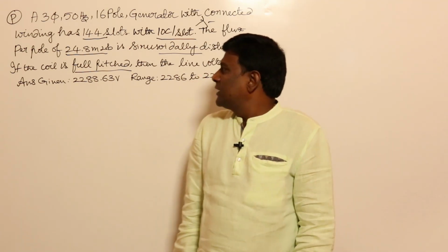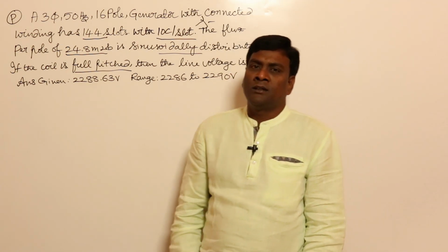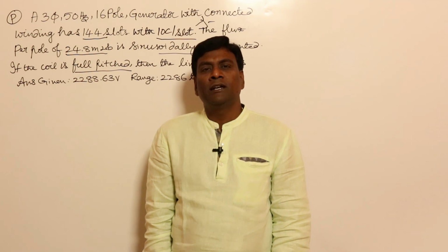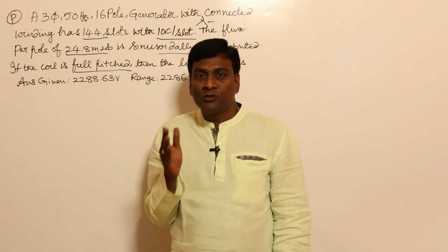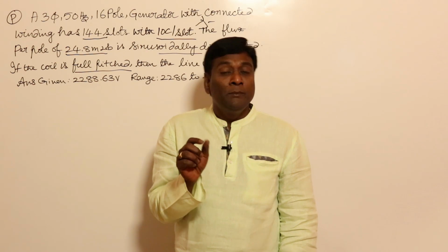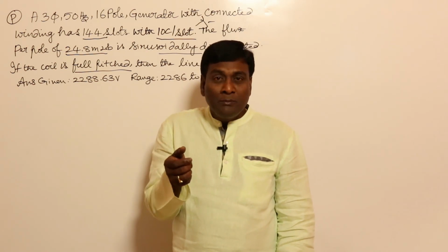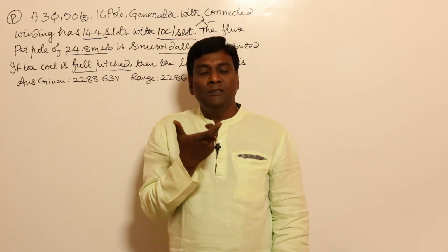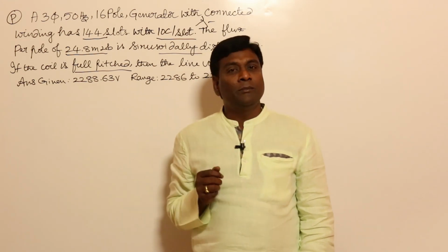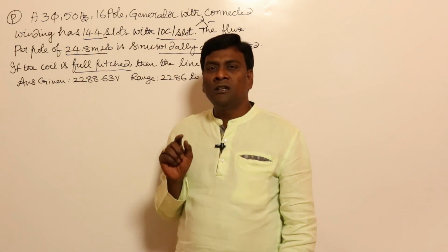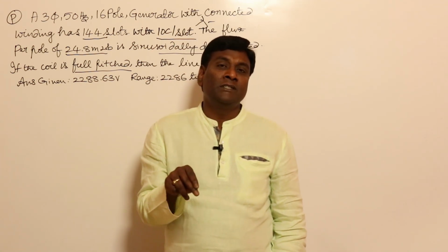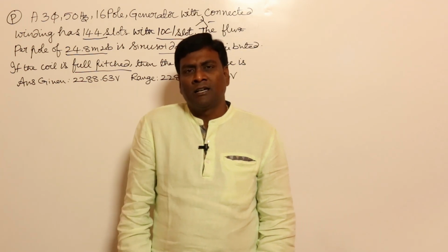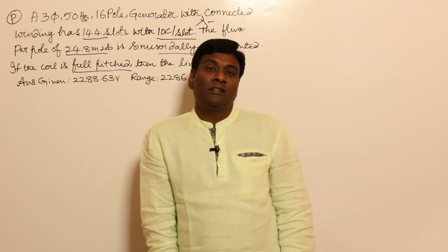The point here is, the moment they say full pitched, as I said in my previous videos on synchronous machines at no load conditions, the moment they say short pitched by some angle, or short pitched by some slots, or the coil span is so many slots, the pitch factor should be calculated. But if they say full pitched, or if they don't give any information about the short pitching angle, we have to consider the pitch factor as 1. We need not calculate it.